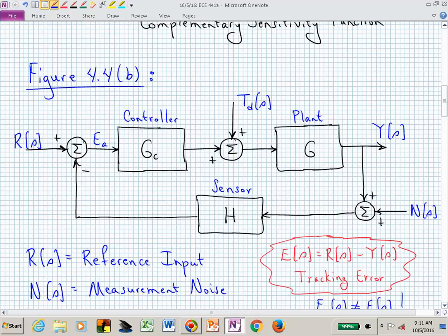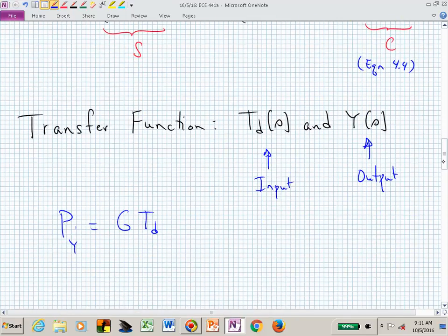Now what do we want? You said loops. How many loops do we have? One, and it has this minus sign, and that's going to be the product of G sub C, G, and H, which if we set H equal to 1, we can say now that our loop is minus G sub C, G, H, which we'll just go ahead and say this is equal to L.